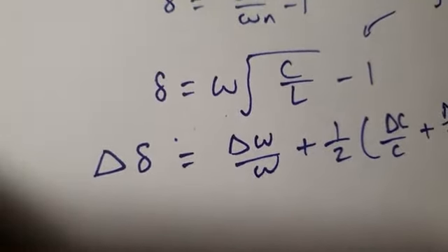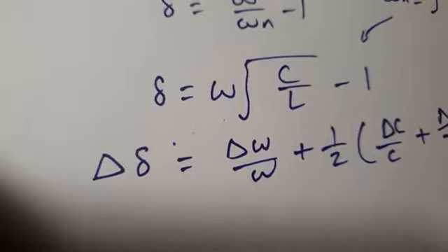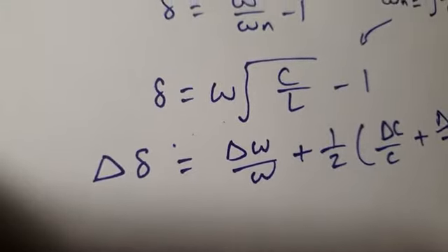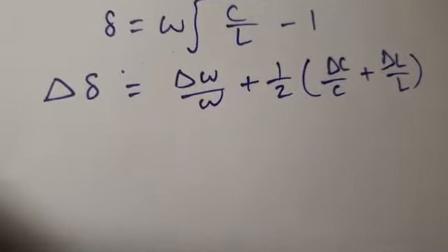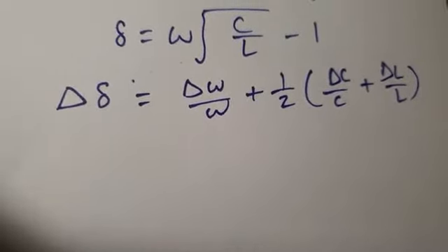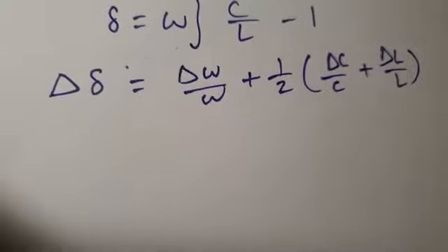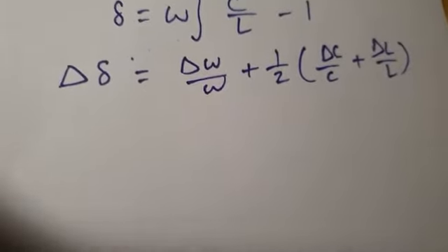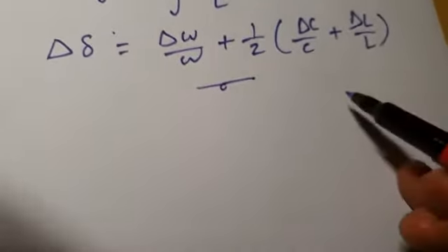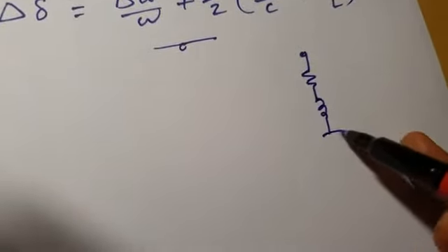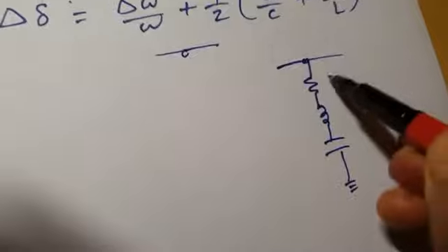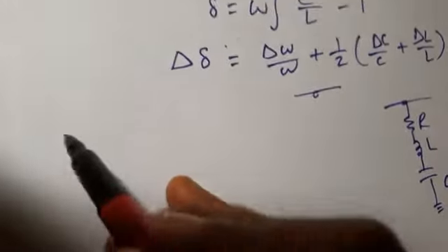Now, once you design the double tune filter, I have already told you that there are two purposes of a filter. Number one, to suppress the harmonics of a particular harmonic frequency, and number two, to provide some reactive power compensation. Let us see how it provides the reactive power compensation. So after this double tune filter, if I take again a single tune filter, R, L and C, this is my single tune filter. Let us see how it provides reactive power compensation.